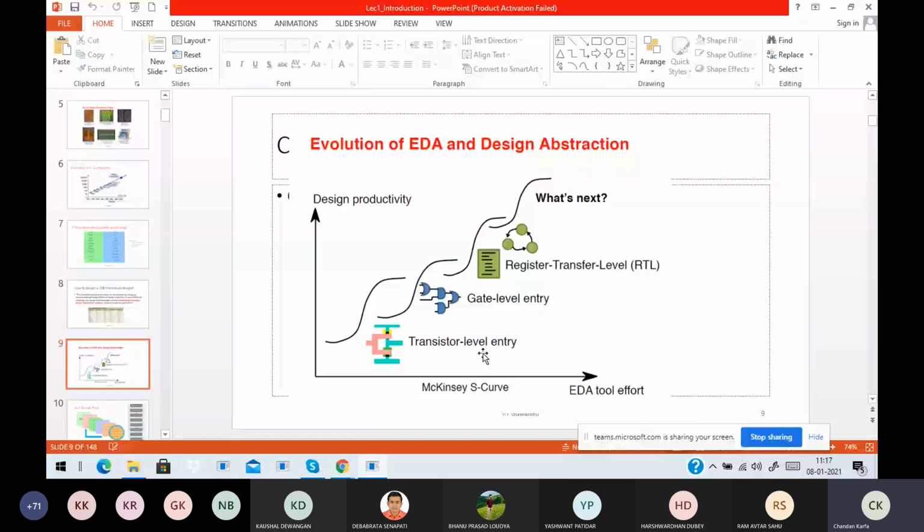So in the register transfer level design, what happens? Think about your digital design class, where you have a full adder. You can always represent it at gate level, but at a higher level you can just think about a node which is doing a plus b. In register transfer level, I abstract that out. I'm not going to represent an adder or a multiplier using a gate level circuit. I'm just going to write out equal to a plus b. A, B, and out are all registers.